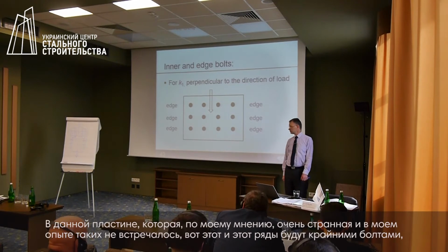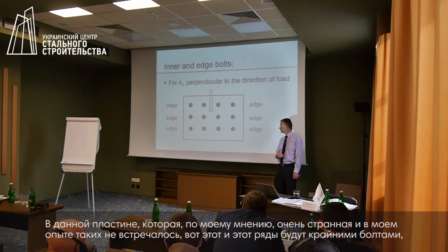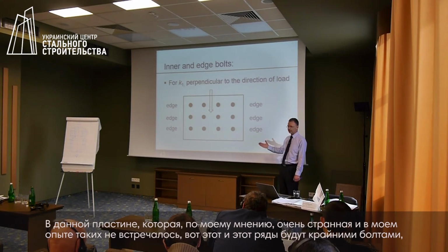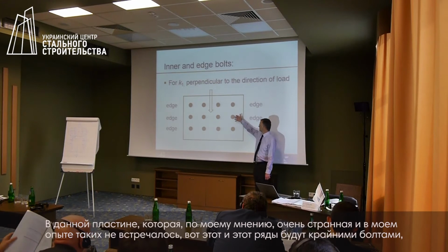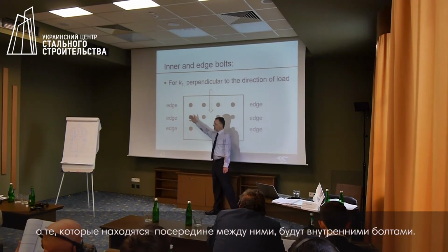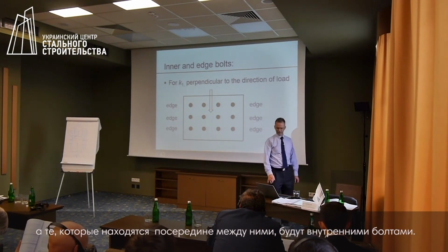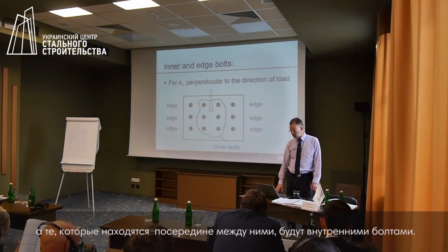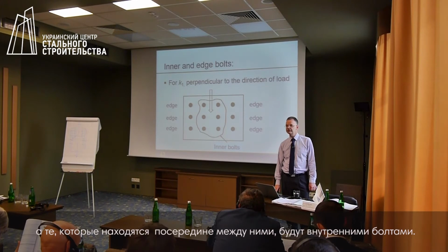In this plate, which in my experience is very, very unusual, I have never seen an end plate connection that looks like this, these would be edge bolts, these would be edge bolts, and the ones in the central zone, they will be inner bolts.